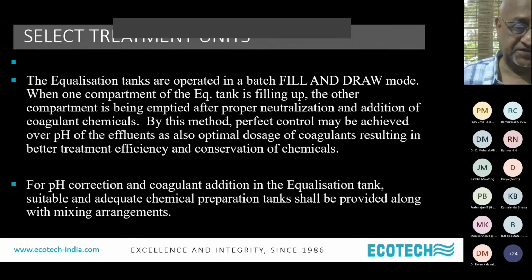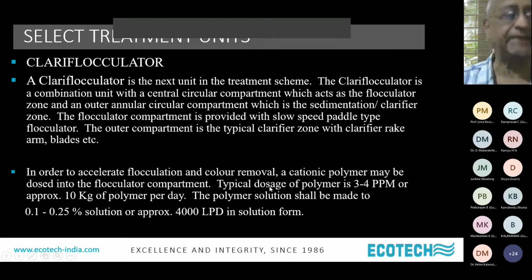Select treatment unit. Equalization tanks are operated in batch, fill and draw mode. 1 compartment, as I said, optimal dosage chemicals. For pH correction, coagulant addition, equalization tank is suitable. We don't do it online.